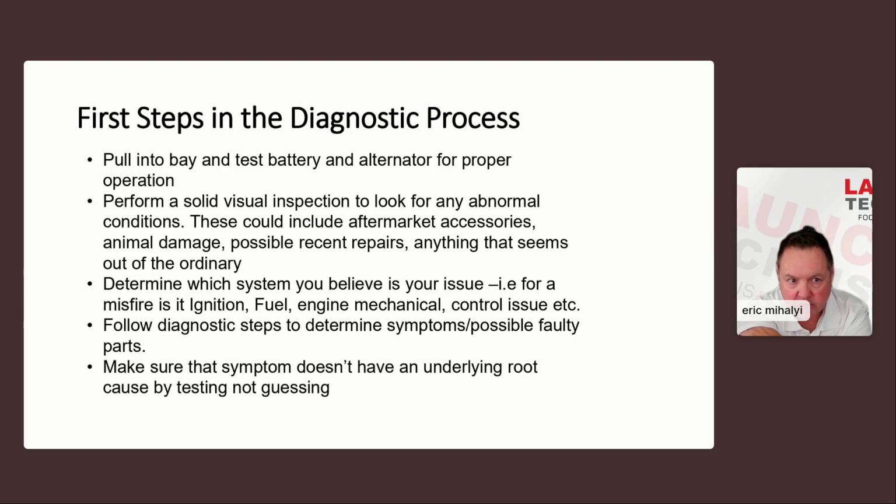That battery sensor sends the information to the ECM, right? So the engine control module is now the voltage regulator, okay? And what tends to happen is as the battery gets weak, the engine control module is controlling the alternator to pump up when the car gets going, and starts having the alternator do more work because the battery is getting weaker, right?